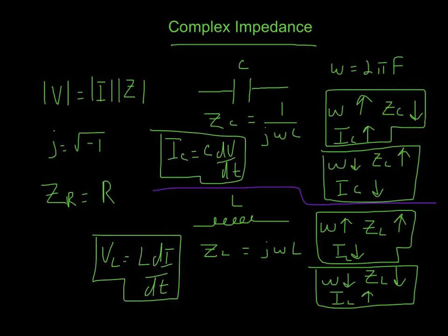All right, so solenoids, inductors, what they do is they resist flow the faster you try to put something across it. So the faster you try to put current through this thing, the faster you change current, the more of a back EMF you get to oppose the voltage.